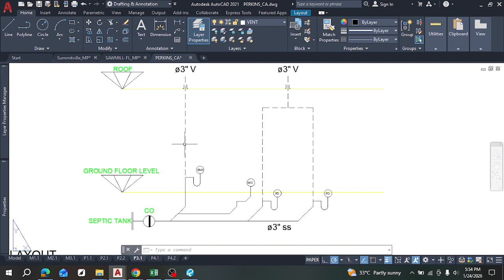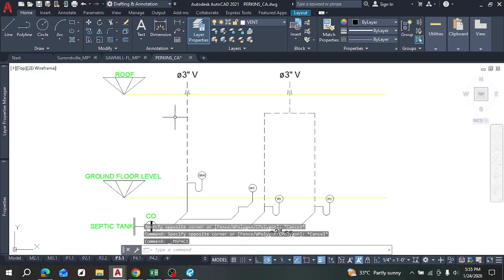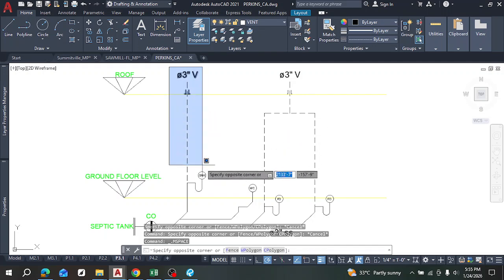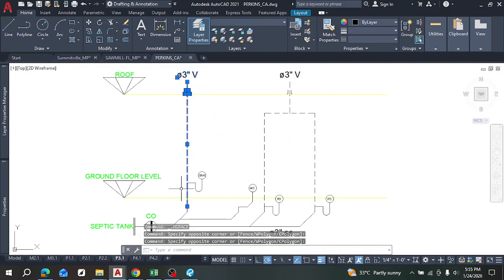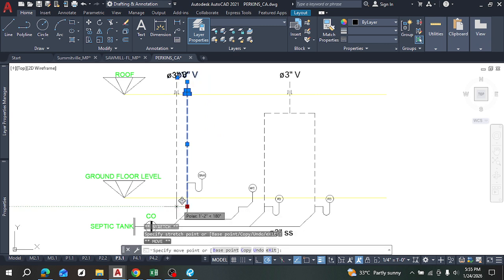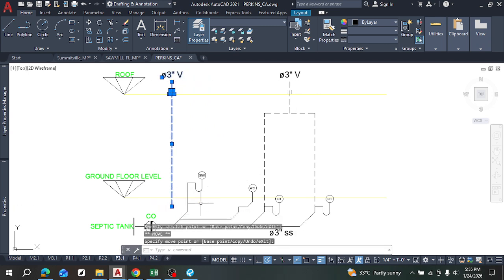Usually I like to vent the WC as I mentioned. So I'm not very comfortable that I removed this vent line because, okay, right, let's just leave it as it is, because they both meet here eventually. So this is still venting off this line, basically, right? Okay, let's do this. Because usually the priority when it comes to venting is the WC, right?